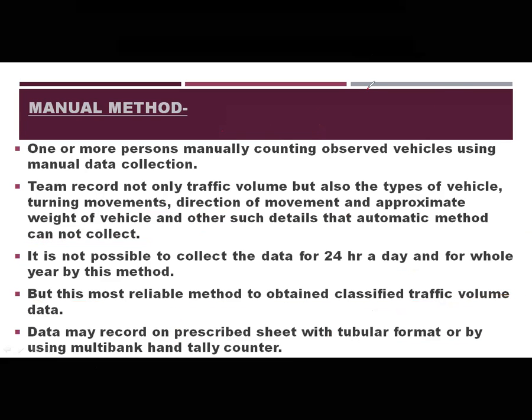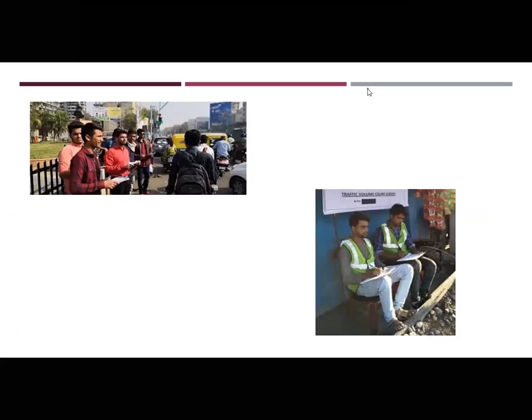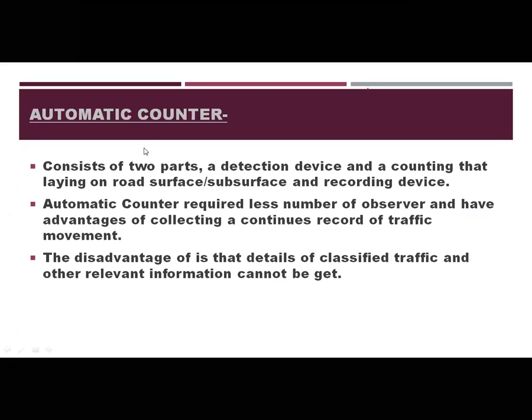Here these are the traffic volume study volunteers or counters. In an automatic study, we could collect data for a long time, but not with great precision. So when a long time is needed and great precision is not required, we use an automatic counting machine.